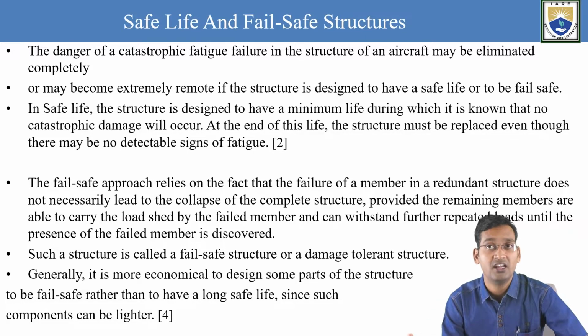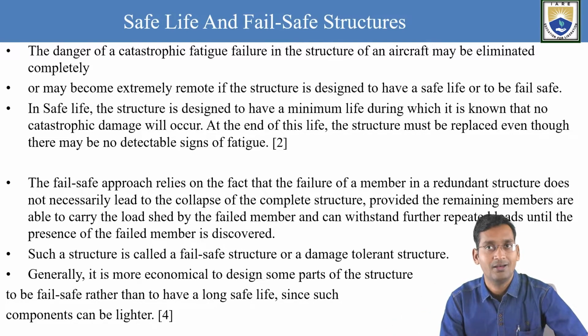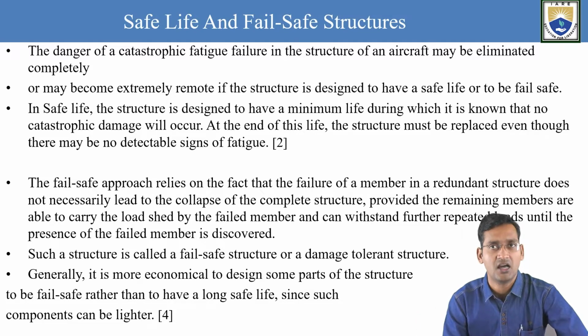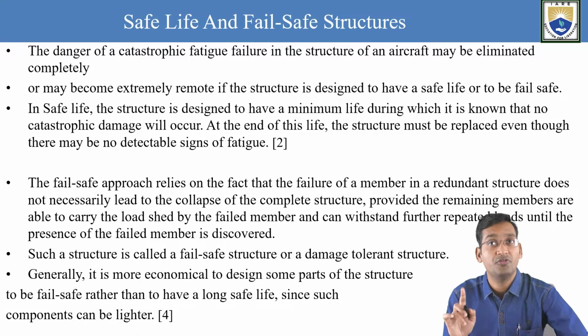Similarly here, if the load that member was experiencing earlier is getting distributed among the others, then only can we change that member. Similarly, like the punctured tire, if those three wheels experience that force and balance the car structure, then we can uplift the car and change the tire. So now the new tire got changed. Similarly here, the last line is: until the presence of the failed member is discovered. So the failed, punctured tire is changed. That is the fail-safe approach.